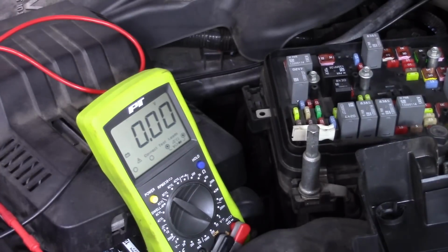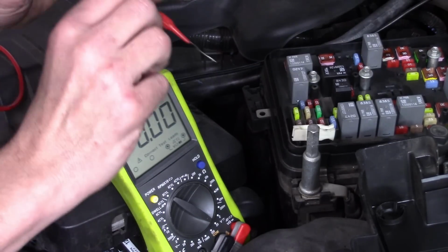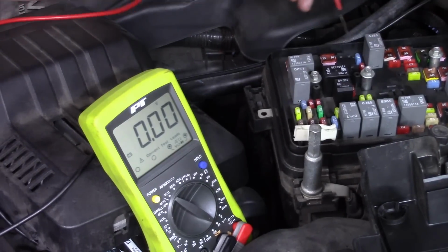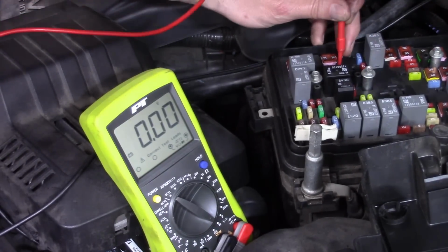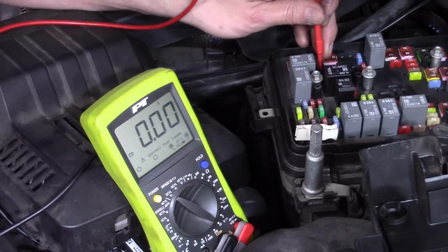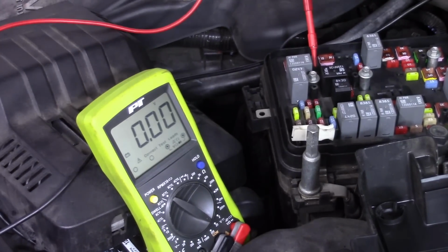All right, now the other question we had is, is there power at all times on the control side? Well, very easy to find out. I'm going to take my DVOM. We're going to test this point of the control side. Nothing. This point of the control side, nothing. Okay, so this is very easy to identify. We are only going to have power come to the control side with key on in this vehicle. Let me go grab a key.